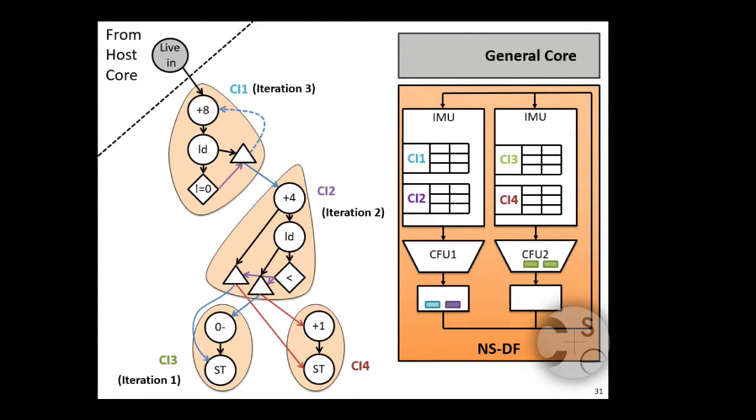So if we compare this to what a general-purpose processor needs to do to get parallelism from the code, it will need to perform speculation of each of these branch decisions. Now, the first branch is very predictable, but the second branch here is actually very unpredictable. And what that means is that either the general-purpose processor would have to serialize on this control instruction, or it will have to suffer misspeculation and recovery overhead. So that's why, for this code, we'd rather use this Dataflow processor.